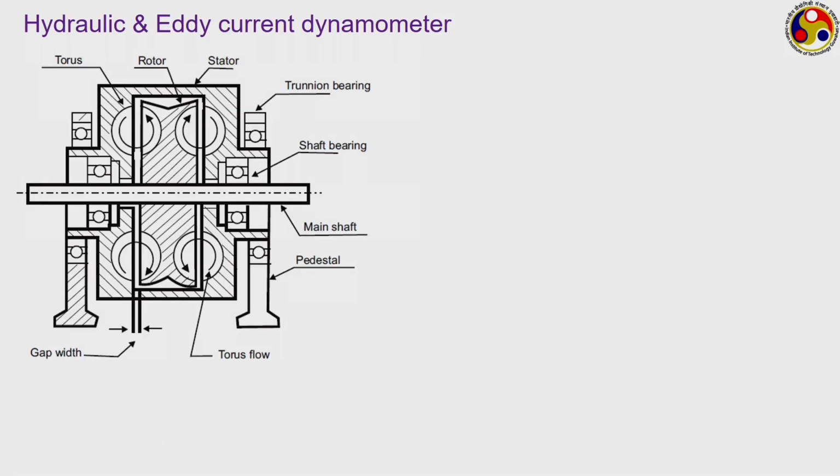Next, the hydraulic dynamometer, a very common device. Here we have fluids which are being circulated around the main shaft, and the power being dissipated is transmitted into the water, so the corresponding temperature we can keep within limit. That is the working medium, which is fluid, I should not say it is water, it can be some kind of oils also, that also act as the cooling medium. That is, it serves a double purpose, both as the working medium and also as the cooling medium.